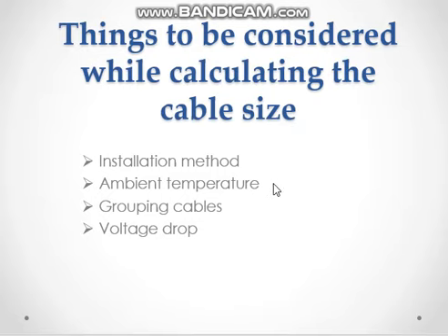The second one is the ambient temperature that you are working in. The third one is the grouping of cables. This grouping includes single core cables and also multi-core cables, and also you have to check the voltage drop.